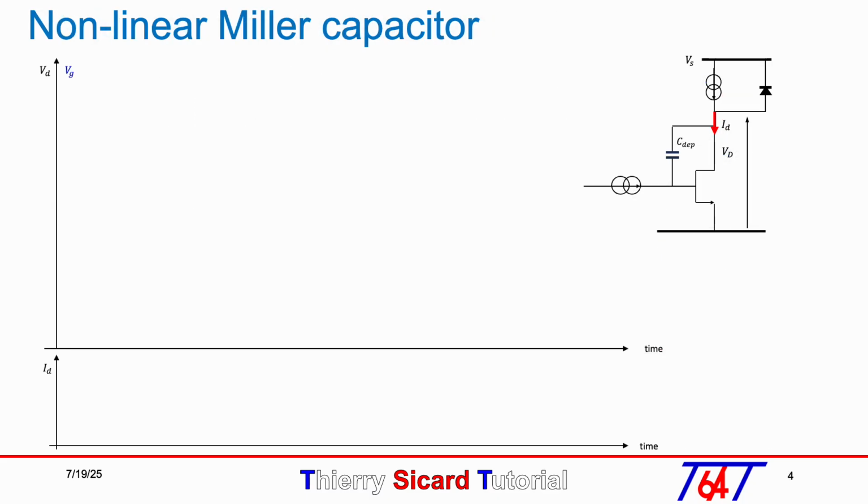The gate is driven by a constant current source. Thus, the gate voltage starting at 0 volt increases linearly up to VGSI. When the gate voltage reaches VGSI, the NMOS can drive the drain current ID. Therefore, no current flows through the recirculating diode D, and the drain voltage is equal to the supply voltage Vs.